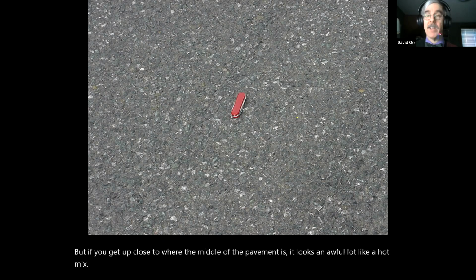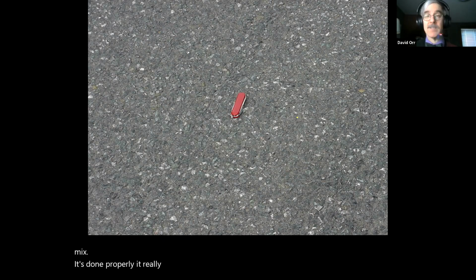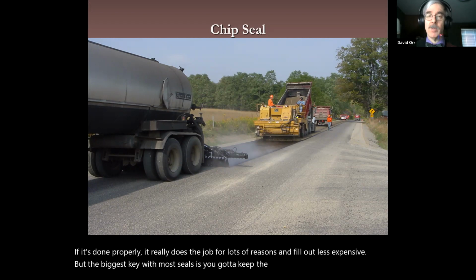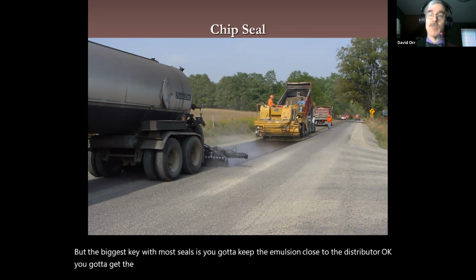If it's done properly, it really does the job for lots of reasons, and it's a lot less expensive. But the biggest key with most seals is you got to keep the emulsion close to the distributor, okay? You got to get the stones down while the material is brown.